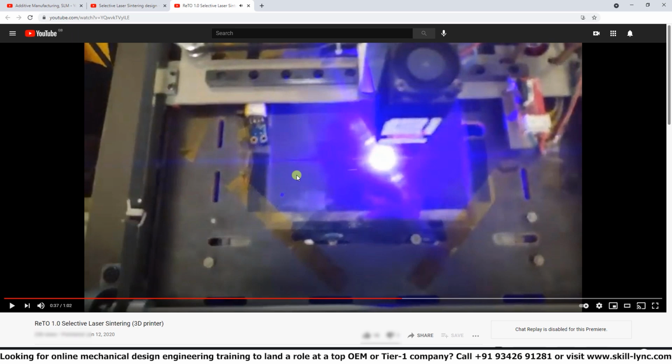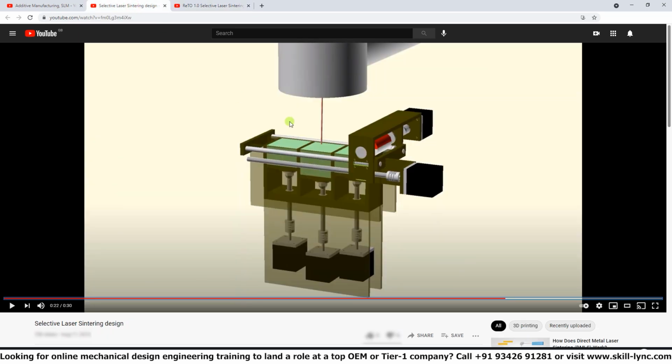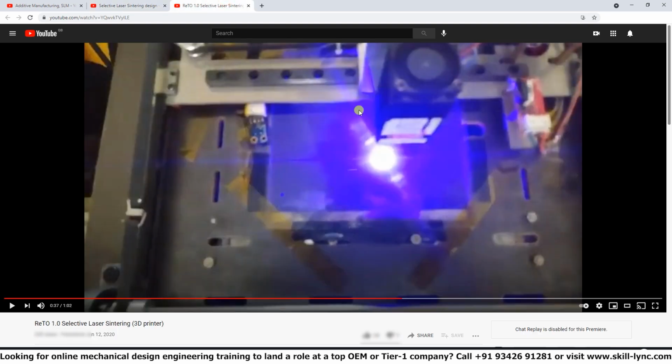So once that powder layer deposition is done, the laser can continue on to the next layer. As you may have seen in this model, as opposed to the previous one, this had a dual feedback, so the roller only had to go across the workspace once. In this example, I believe it only has one material feedback. So the roller had to go across once and come back, return to its home position.